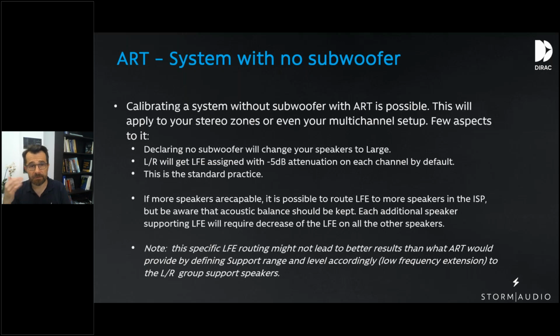You can just define your setup without a sub and use ART in a great way. What you need to know and keep in mind when you go into such a setup is that you will define your systems without subwoofer. When you do that, by default, the ISP will drive the LFE signal directly to the left and right speakers evenly with -5 dB. This is the standard practice.